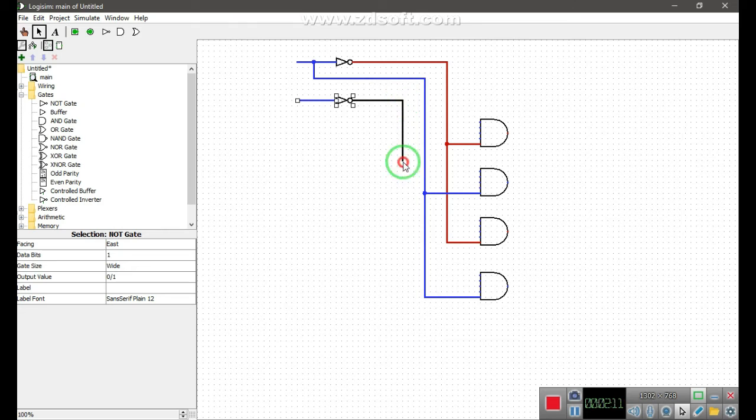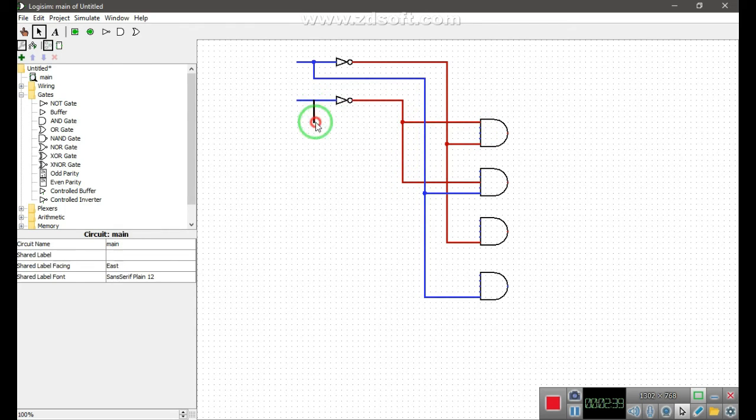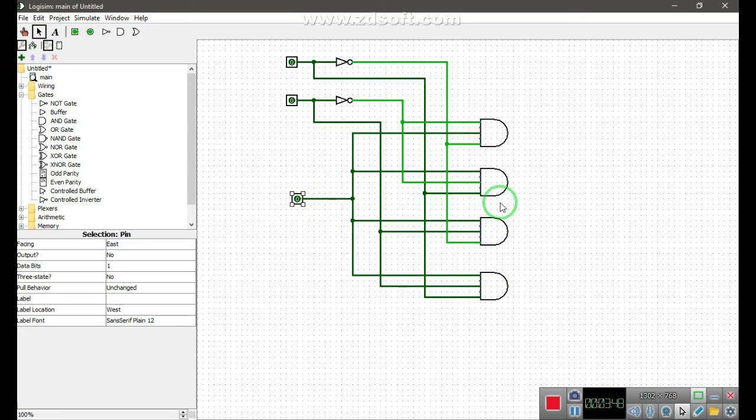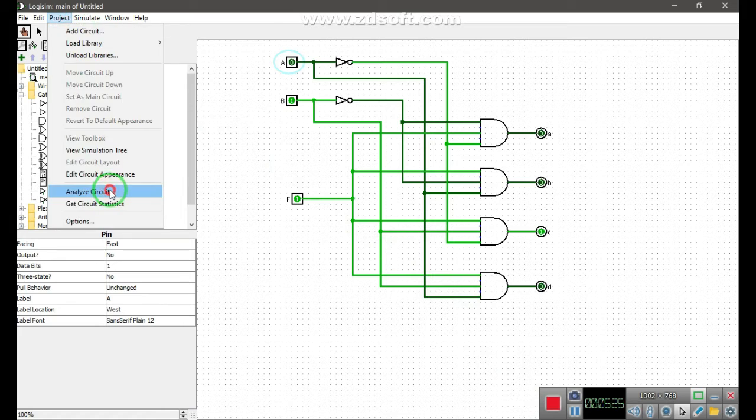The multiplexer takes one signal input data line and then switches it to any one of a number of individual output lines one at a time, and the demultiplexer converts a serial data signal at the input to parallel data at output lines, as shown in this example. So here also we can see a truth table like the other example.